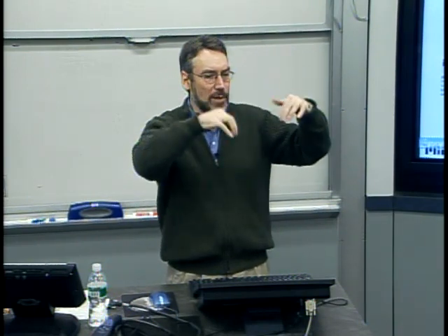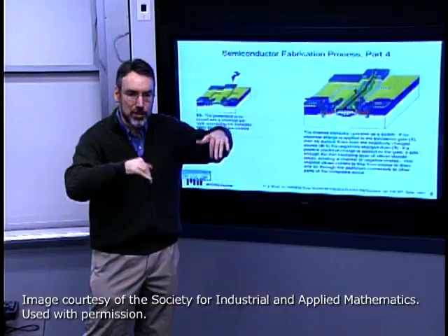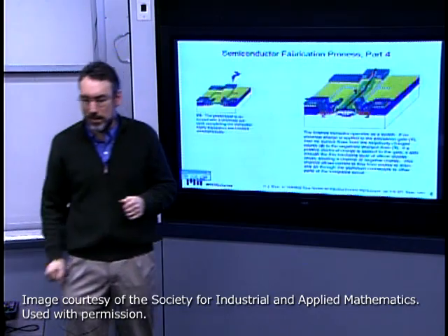At that coarse level of 3D, I would say several memory chip makers are already doing chip stacking within one package. So in some of the memory chips, if you were to etch away the black packaging and casing around one of those chips, you might find a stacking, but they are not heavily electrically interconnected. It's not a fully integrated structure. In fact, at the end of the day, they typically have bond wires, big macroscopic wires coming in the sides of the chip separately at each of the stacking.